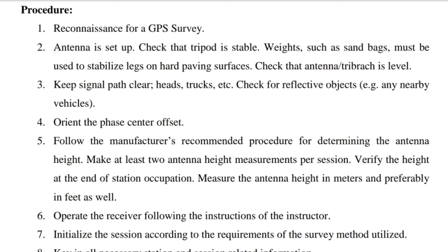4. Orient the phase center offset. 5. Follow the manufacturer's recommended procedure for determining the antenna height. Make at least 2 antenna height measurements per session. Verify the height at the end of station occupation. Measure the antenna height in meters and preferably in feet as well.